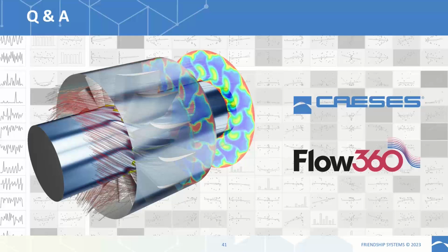Yeah, maybe in a similar direction, there is a question regarding how the best geometry differs from the baseline. So I don't know if you could see it, but there were some pictures in Payam's presentation that showed the difference. So basically, the main difference that you can state is the baseline geometry, as you can see in the backdrop here, actually was a straight blade, very simple straight blade shape with constant parameter values throughout the span. And as a result of the optimization, we got a kind of more wavy geometry, wavy shape, where individual span-wise positions and span-wise airfoils try to get the shape where they influence the flow field behind in a favorable way.